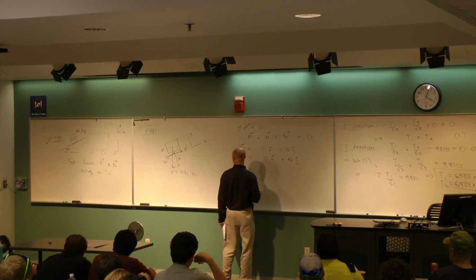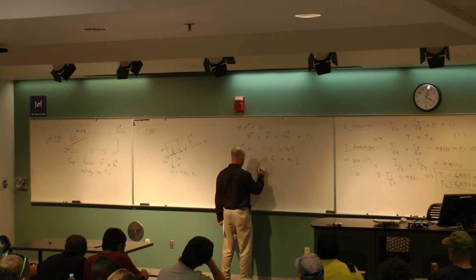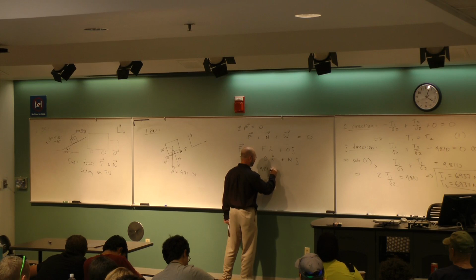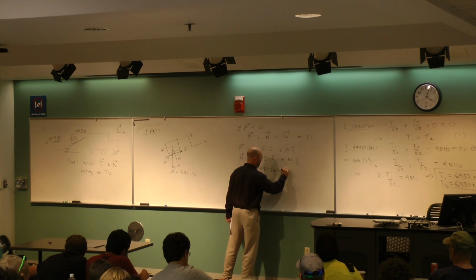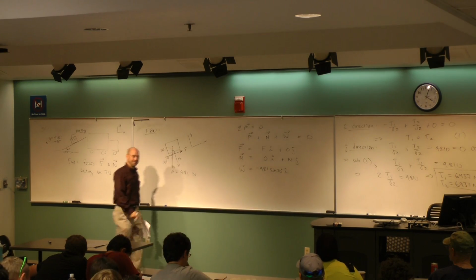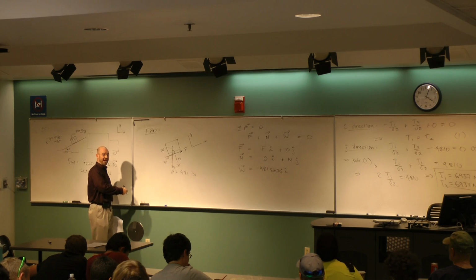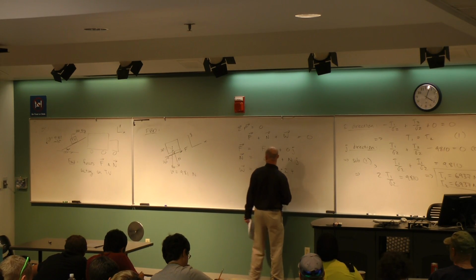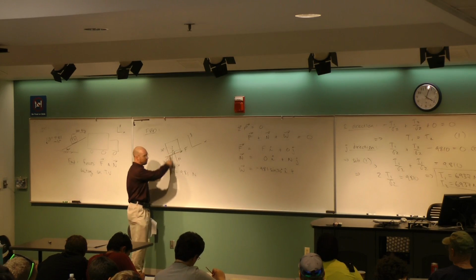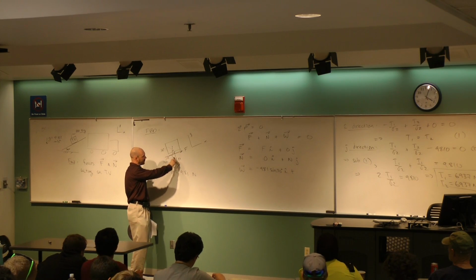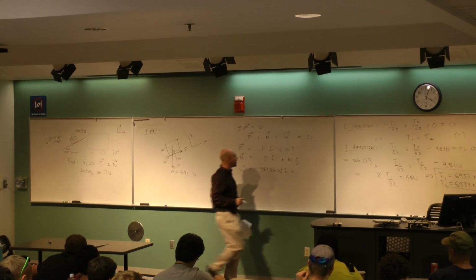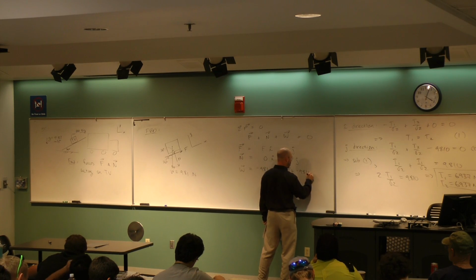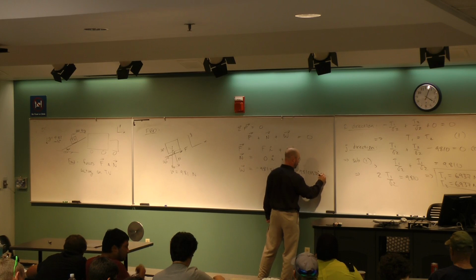So I would write this as the weight, which is 981, going down, times the sine of 30 degrees i. So there's an example of the x component actually being a sine, not a cosine. Okay, and then the y component, which has magnitude 981. In this case, the way I drew it, the y is the adjacent. So it would be minus 981 cosine 30 degrees j.